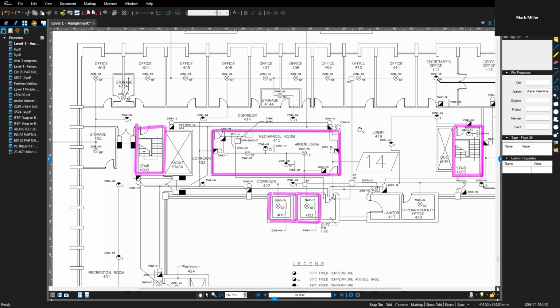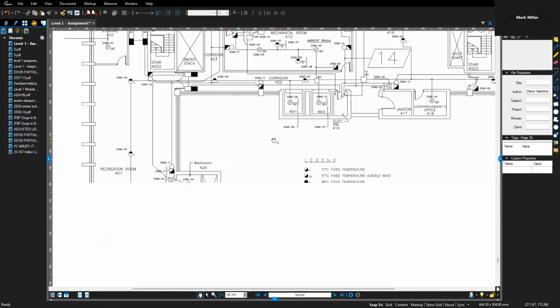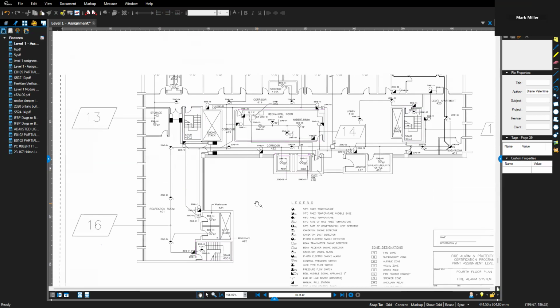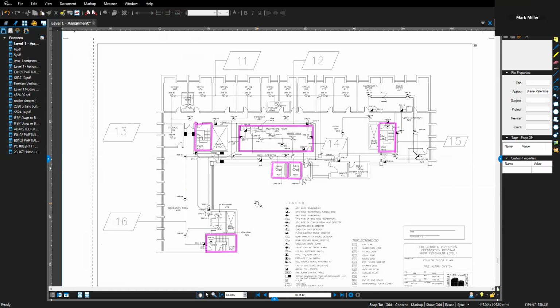It's got a 1 hour fire separation, not a 2 hour fire separation, because it's just an electrical room. It's got some panels in it. It's not like it's a hydro vault with the high voltage, because those get their own fire separation. Okay, so that is actually the extent of the fire separations in this building. So I like to draw them in like that because it makes it easier for me to figure out exactly what's going on. And it's a good place to start, especially when you're looking for missing devices. It draws your eyes to the more special areas.